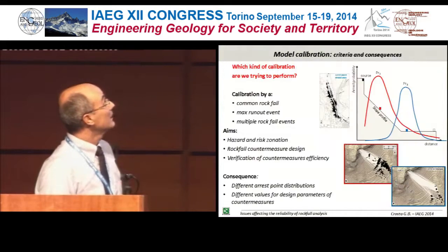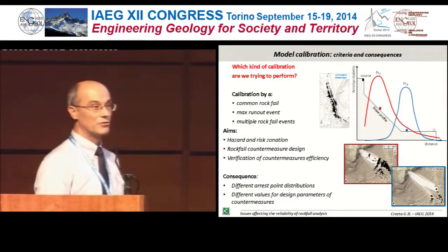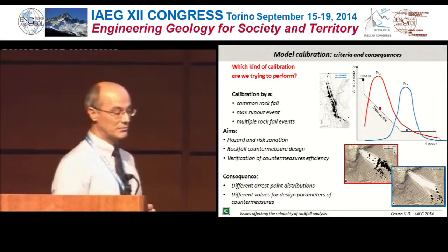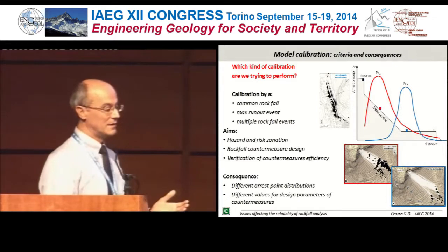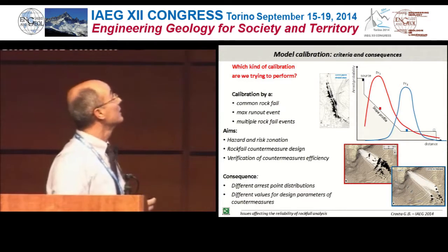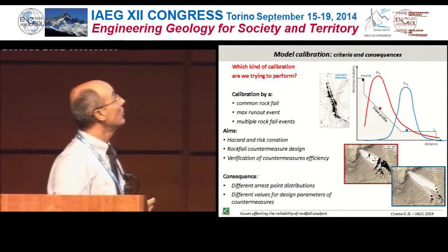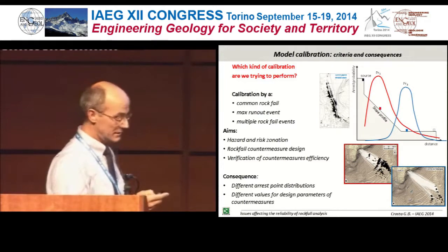The other problem that we have in calibration is why we are performing the calibration on which data set we are working on. So one of the approaches is that calibration is just for a common rockfall that we are expecting, or for finding out the maximum runout event, or from multiple rockfall events.